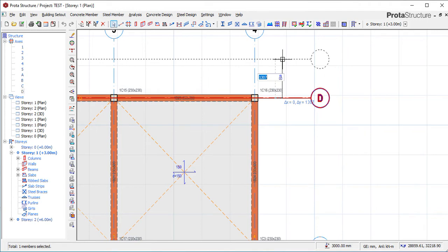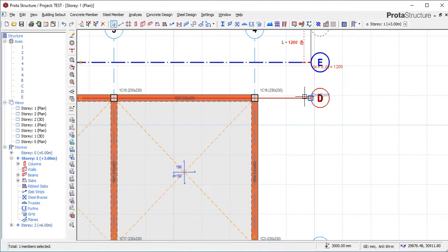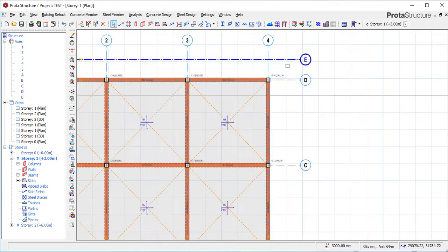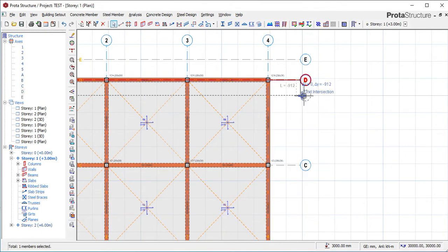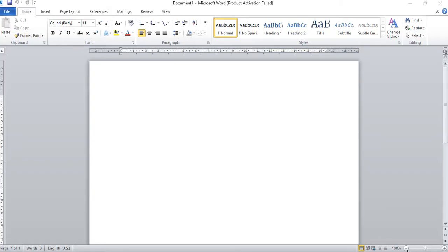It will pop up a box for you to put the distance. Let's assume you want to put 1.2. This is how you offset. But pay attention, if I'm offsetting downward, I click the function key and F2. You hold down the function key.